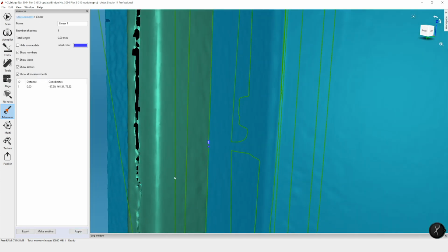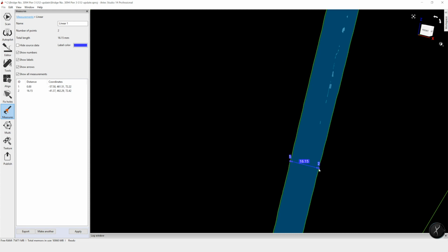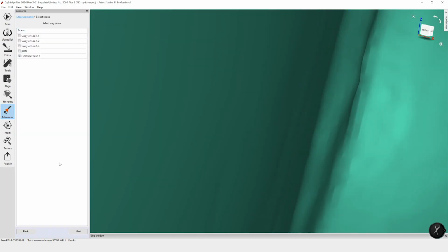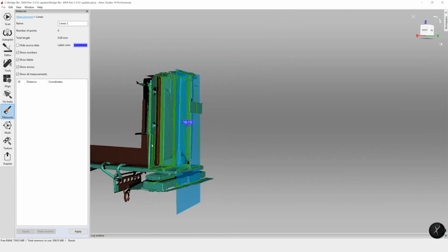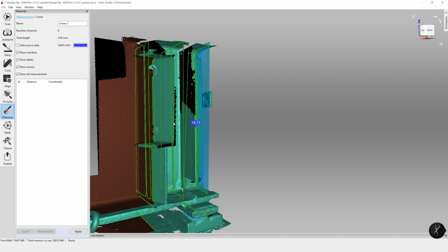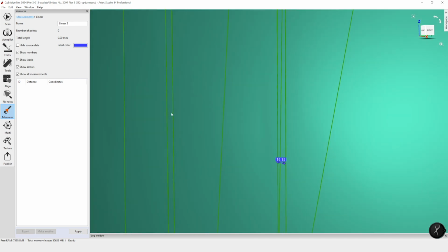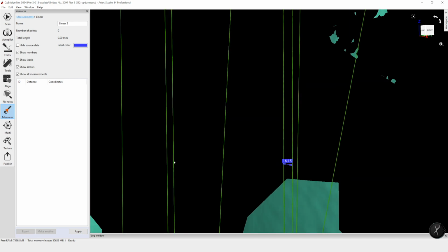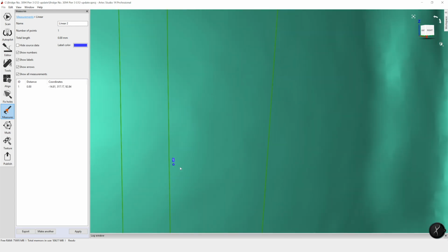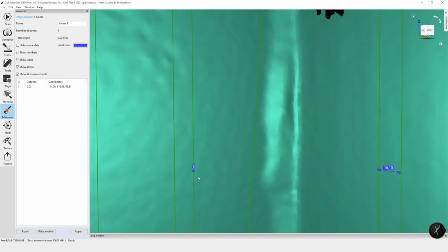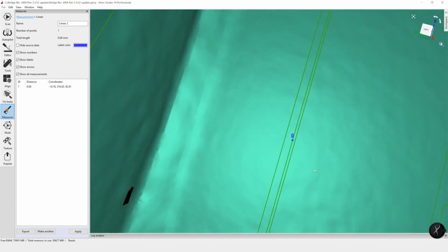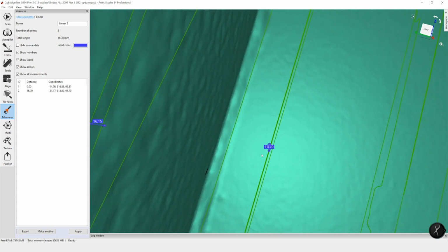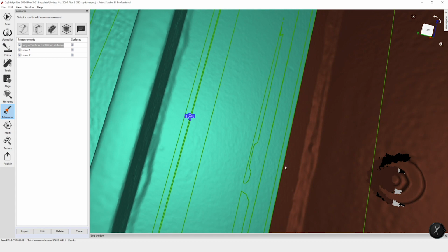So go in, you make those sections, and then remember you're picking the points on either side of the web. Picking points is one of the most frustrating processes in this step. It's interesting to me that it's easier in the alignment to pick points than it is in here, but you want to go over and really make sure you're picking the correct points. This is what we're using to make our judgments on the beam thickness, so we need to be absolutely certain that we are picking the right points. So go around, make sure you're taking it on one side and then rotating the beam around to get the other side, and you can always go inside the beam if you need to make slight adjustments.